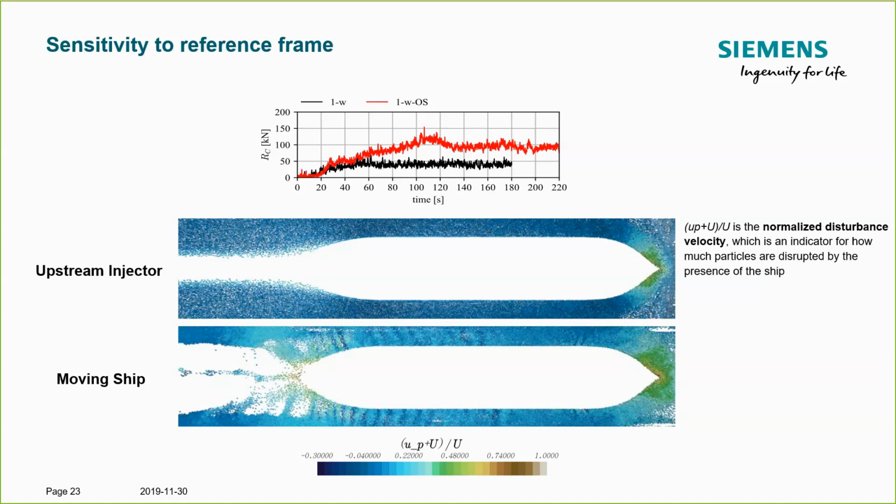So they are less prone actually to exchange momentum in a lateral side or also vertical side, which for very large particles and high particle load density, this would not be quite realistic. So this is basically evidence that if you meet the criteria that you have high particle count, large particles, then to be on the safe side, you should use the overset mesh method, the initial ice field in the channel, and have the ship plow through it in the consistent reference frames.